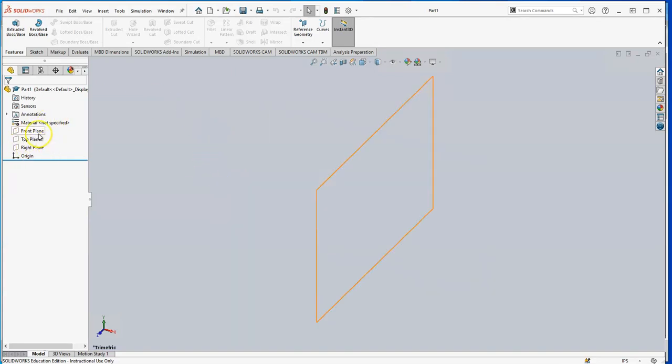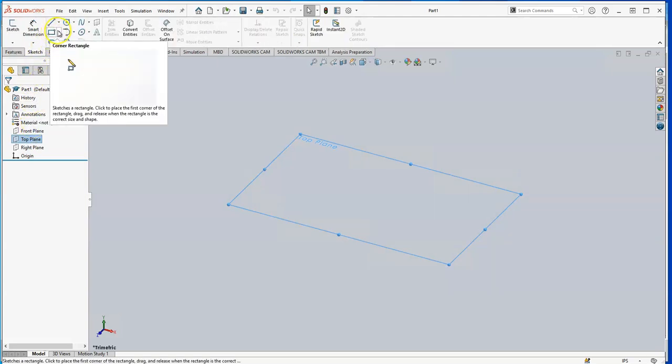So once it's opened, the way we work in SolidWorks is we create two-dimensional objects on flat planes and then do things like extrude or revolve these into 3D shapes in order to create 3D solids. We're going to create a 3D rhombicuboctahedron solid, and we're going to start with creating a single face on a horizontal plane. So I'm going to choose the top plane, and I want to put an object called a sketch on that. And that sketch is going to be a square.